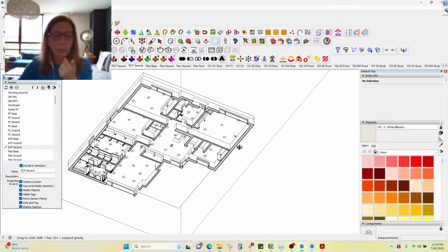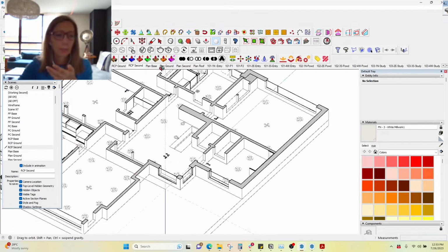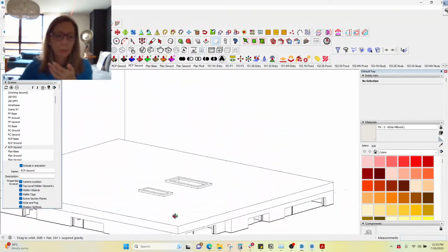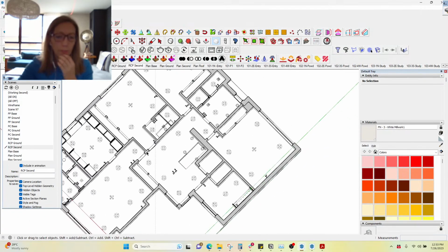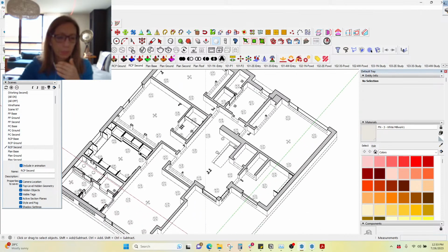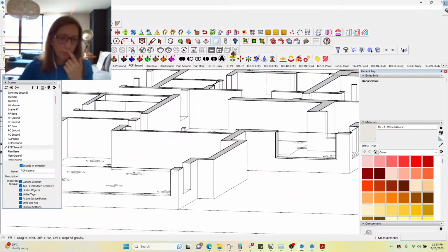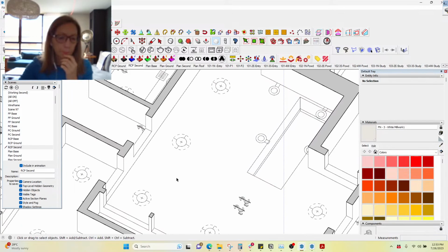And for me it's important to do that because I often have elements in the ceiling that I need to show. Like for example, in this particular model there's 2 skylights. So those need to show, and I also want to show things like headers and doors or millwork that's touching the ceiling. I need to see that. So I usually put the symbols either right on the ceiling or hover them an inch or 2 below. And then in layout, the viewport just gets flipped so that it looks like it's the right way around.